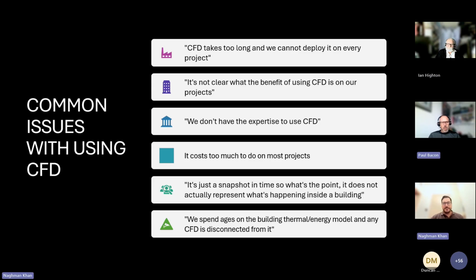And the other problem with common CFD is it is just a snapshot in time. At 1 hour with a certain wind speed, a certain wind direction, you get this result. What happens the next hour? So the dynamic CFD gives you that opportunity to look at more of a full day or even longer if you wish. Yep. And that's quite novel, and I think that's important because a lot of our user base and people out there are used to dynamic simulation or dynamic thermal modeling.